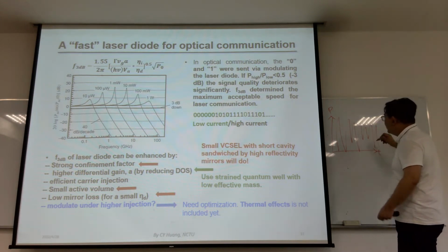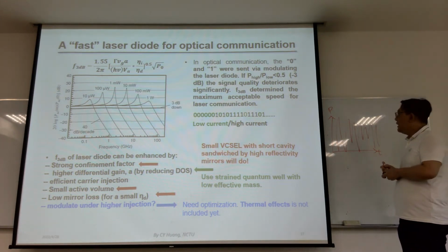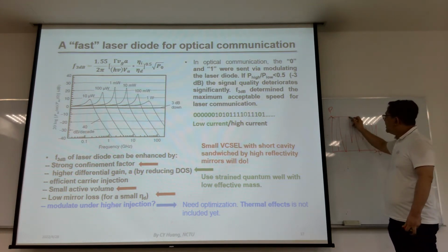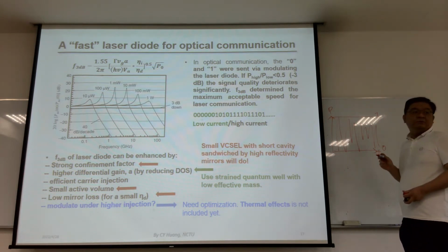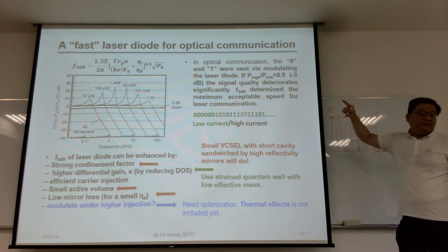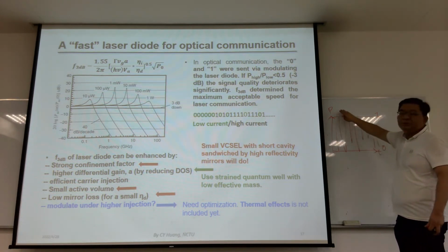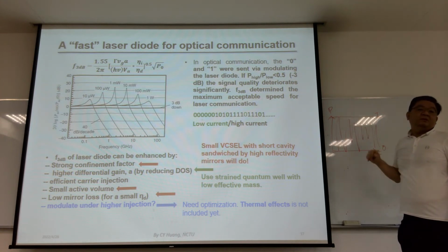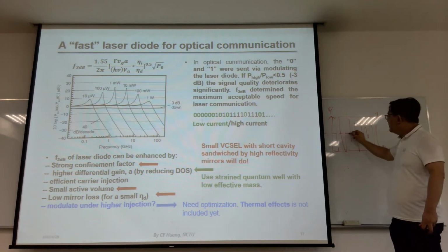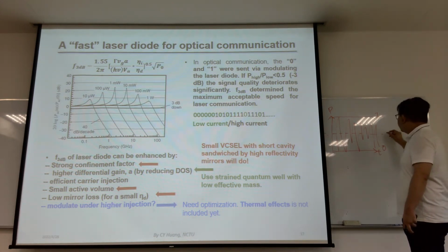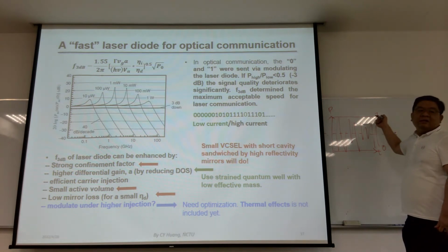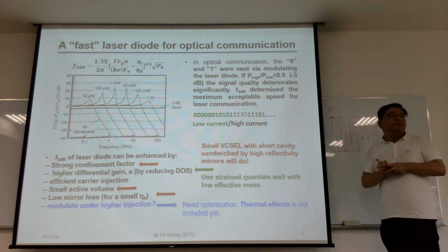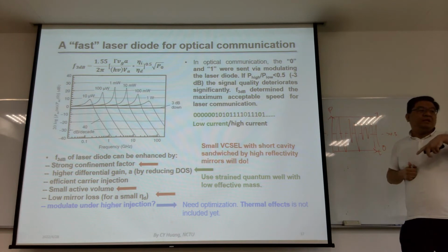Okay, so it's pretty complicated. Because it has high and low, it will find its maximum value called 1, and its minimum value called 0. Because the signal might always reach 1, or sometimes even surpass it, what it will do is detect if the signal is larger than 0.5, it is read as 1. If the signal is weaker than half, then we count it as 0. So then we can further transfer the optical signal back to the electrical signal.